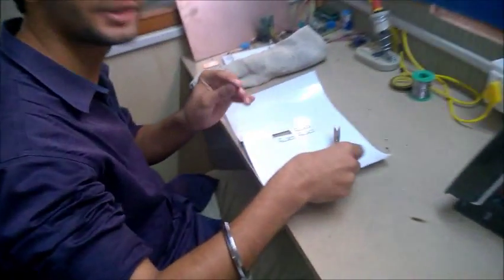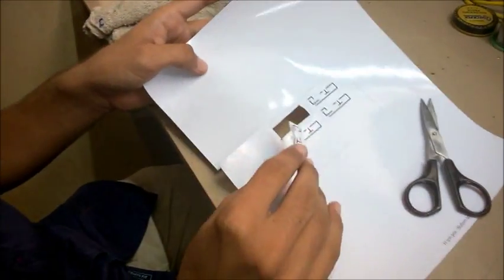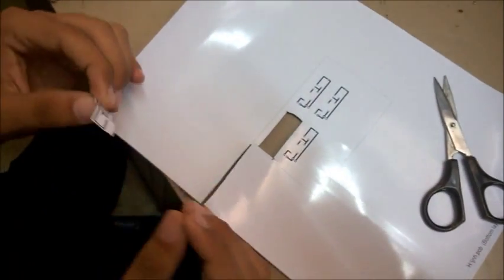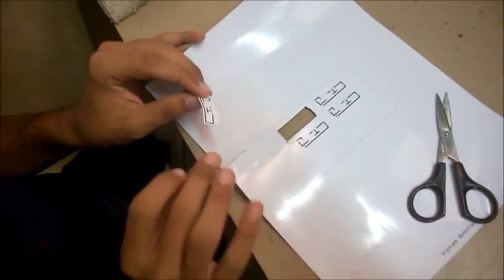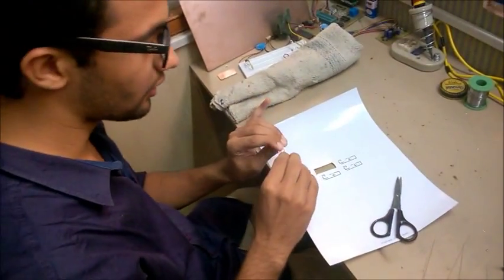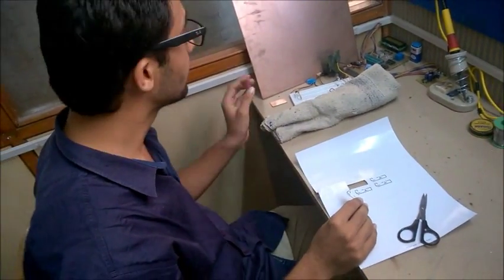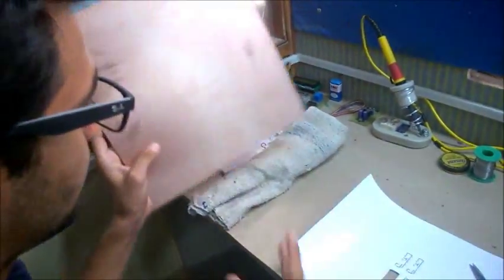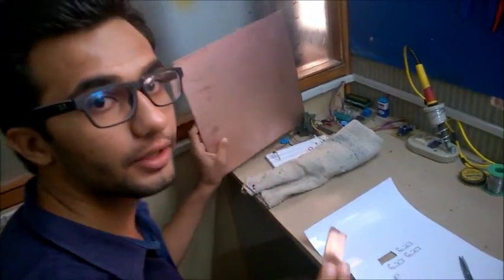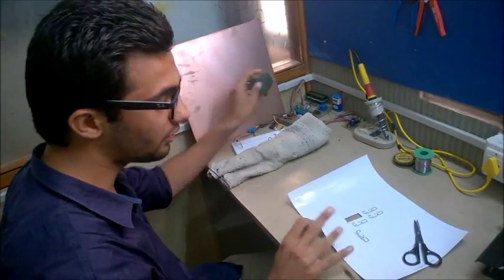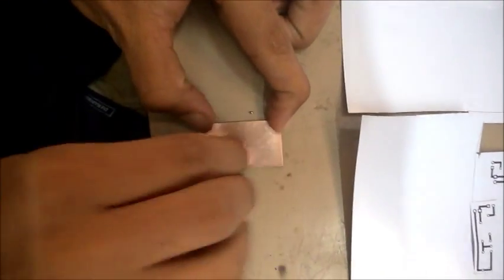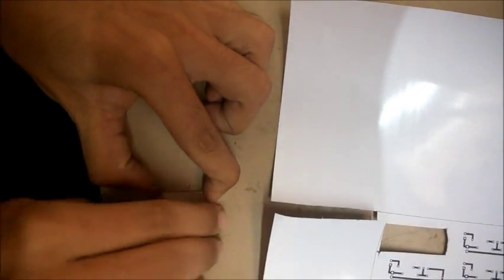So hello, I have just cut the circuit diagram from the printout. See, this is the printout. I have taken 4 printouts, as I told you that if after ironing the circuit diagram is not clear, you can scrub it off. I have just cut it. After this you will require a PCB. This is a glass epoxy PCB. It is easily available in the market. This is a better one. Now you have to cut this. I have already cut it. Now you need to scrub it because it is a bit rusted on the surface layer. You need to scrub it till it's shiny.